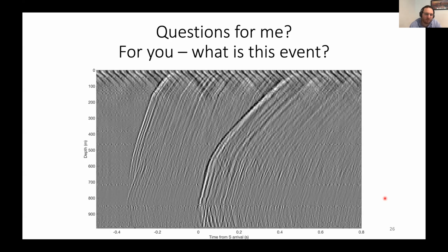We found that an automatic slant stack approach, which basically means you try to automatically fit different linear velocities to portions of the array. So you take a portion of the array, let's say 100 meters or 150 meters, and you try to give it a best linear fit that maximizes semblance or some other coherency measure.